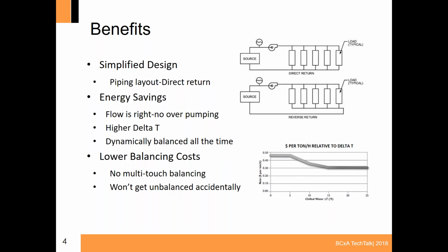You might have a coil that's leaking on startup, and you might have one of the mechanical contractors going back and shutting off the system at the balancing valve, and perhaps the balancing valve didn't get marked properly. And okay, we fixed the leak and we turn it back on. Well, that valve had been balanced, and now when they turn it back, they might turn it wide open, and now we lose the balance on that device, and that also impacts all of the other surrounding valves.